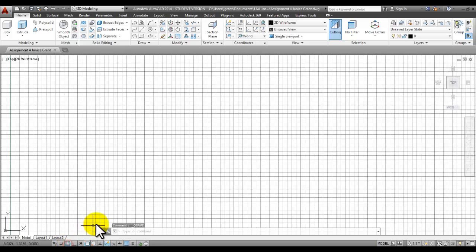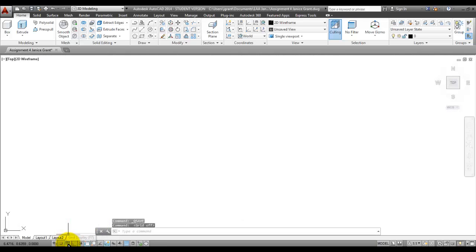I generally turn the grid off. It's up to you. The book lesson uses construction lines created in kind of a grid so that you can draw on a grid. So there are, as you know already, several ways of doing this. I'd want to show you one way of drawing this in 2D and then turning it into a 3D solid. So we can start the line command.